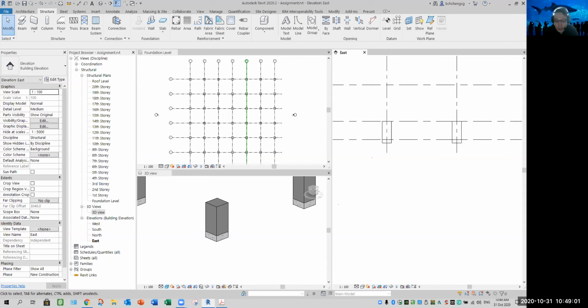Huh? Zoom extend? What don't you know how to do? Your mouse, your auto scroll, just double click. Or if not, at the keyboard, just type ZE.